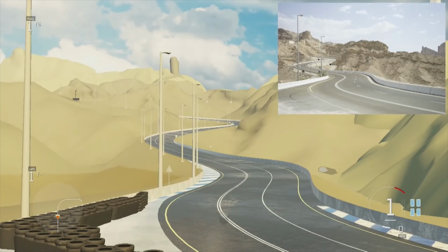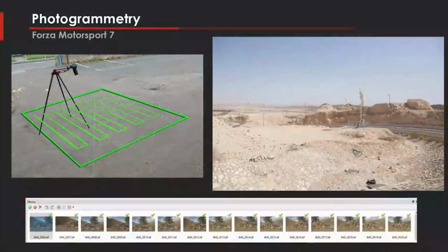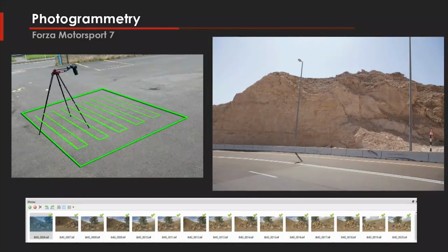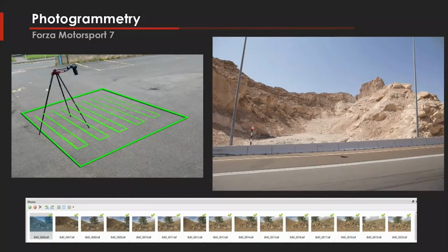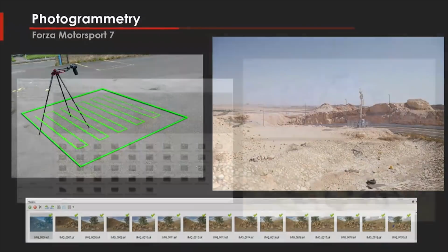scan data. And this is informing us where we're going to start breaking down that photogrammetry. And from there, we're going to start replacing that with our final in-game assets that are generated off of the photography that we took on site. And so if anyone's not familiar with photogrammetry, the quick overview is that photogrammetry is made up of taking a whole lot of photos of a real world object, then using software, we use a combination of Agisoft Photoscan and Reality Capture to calculate all of the trajectories off of those images and figure out how you would recreate a 3D mesh off of those.